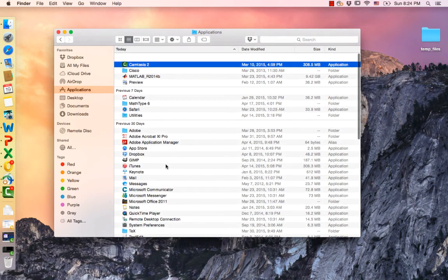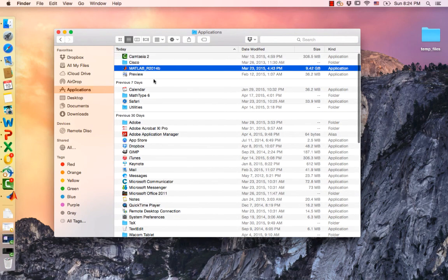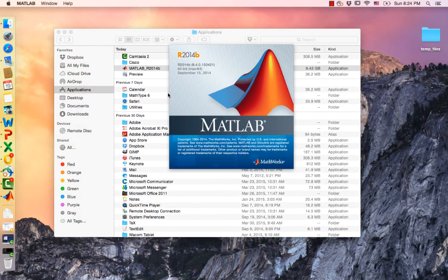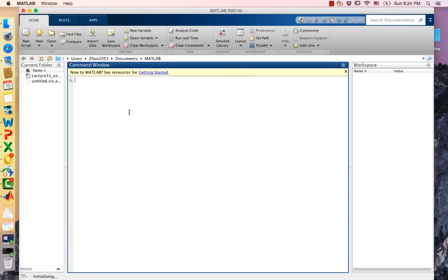So we probably need to modify something else, to make the time step longer, so that we do not have too many data points to simulate. Let me start Simulink again, the same thing. Yes, they saved my previous Simulink windows.